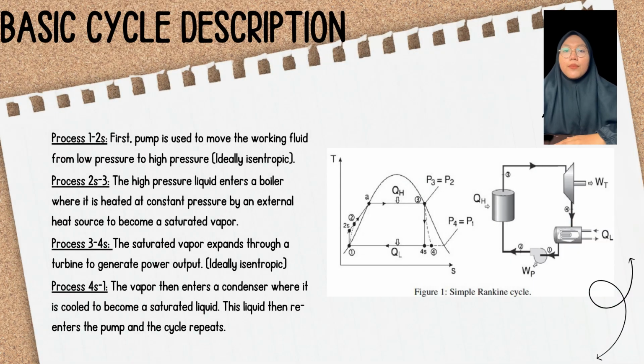The Rankine cycle describes the operation of steam heat engines commonly found in power generation plants, as schematically shown here. In such a paper from WIT Transactions on State of the Art in Science and Engineering, power is generated by alternately vaporizing and condensing a working fluid. In many cases it is water, although refrigerants such as ammonia may also be used. There are 4 processes in the Rankine cycle, each changing the state of the working fluid. These states are identified by the numbers in the figure given.